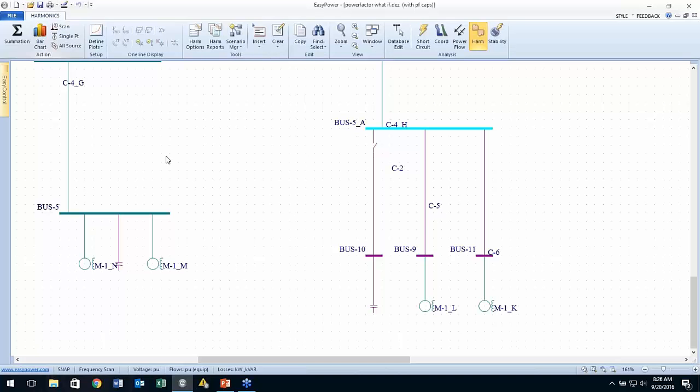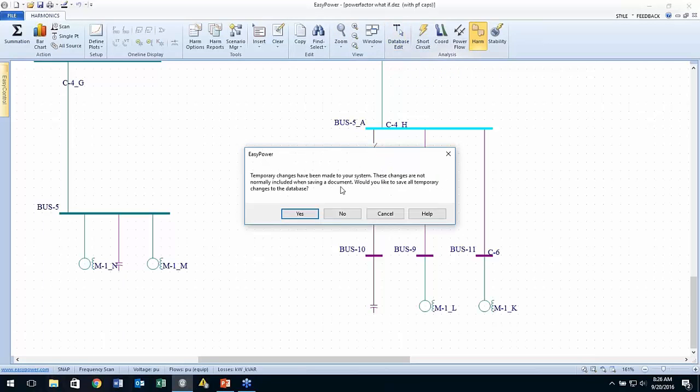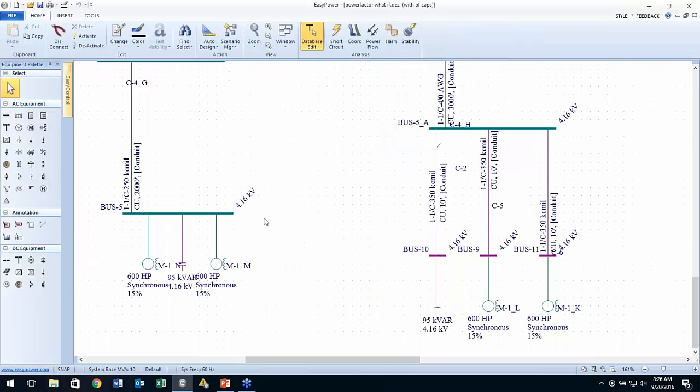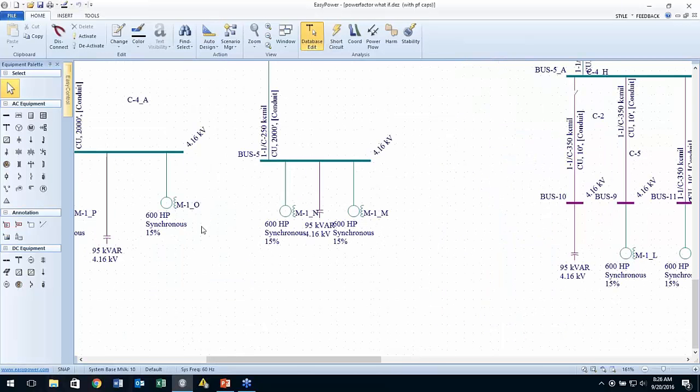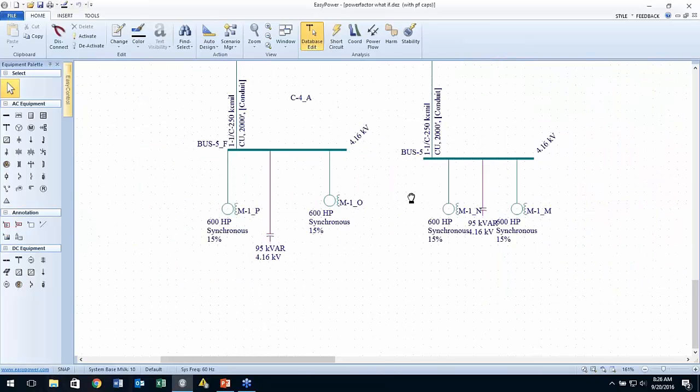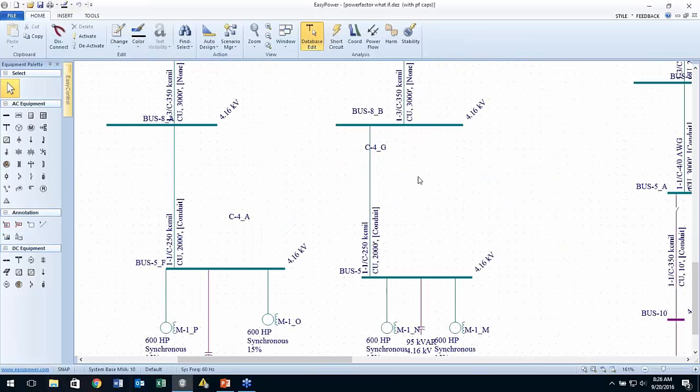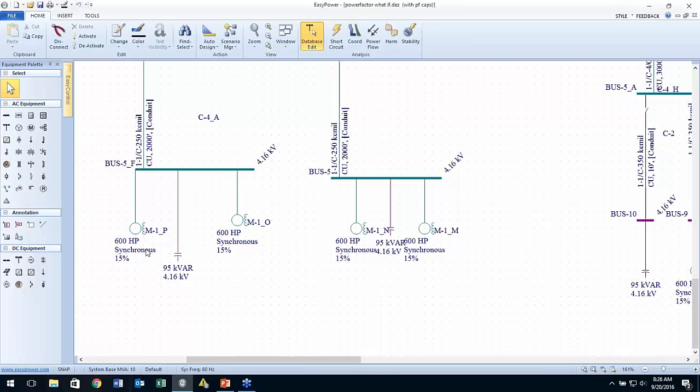Now, that's not necessarily harmful as long as I don't have frequencies at those resonance points. So now the next question becomes, what if any frequencies do I have at those points? Well, in the current database, because we're using synchronous motors, I have not entered any harmonics. So what I'm going to do, just for grins, is say, well, instead of a synchronous motor, what if we go ahead and put in a VFD?